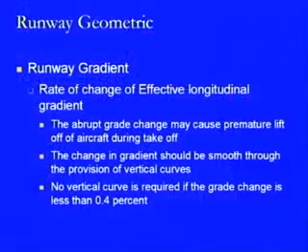Now when we talk about this longitudinal gradient, we can also talk about the rate of change of effective longitudinal gradient. In this case, what we have to look at is the rate at which the effective longitudinal gradient is changing, and that should not be abrupt.